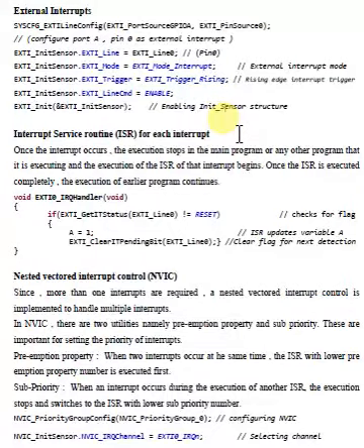This is all I have to do in terms of establishing the interrupt, and next I have to implement something called an interrupt service routine. That is, when I have an interrupt, what do I do? This is a pretty small part of the code. Basically I have three different Hall sensors, A, B, C. The moment I get this particular status flag as high, not equal to reset, basically if it is set, I make Hall signal A equal to 1, and furthermore I use this in the part of the logic to change the commutation of the phase and so on.